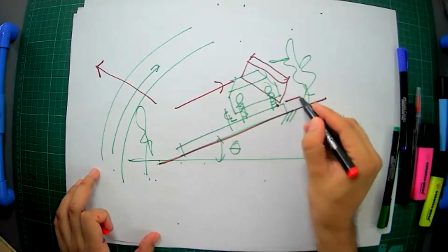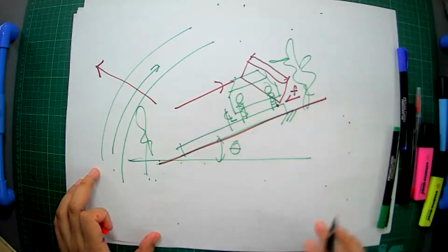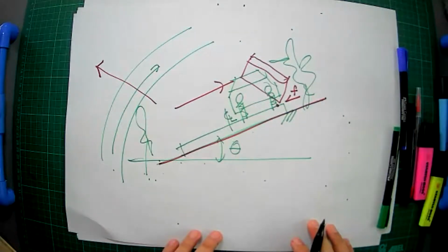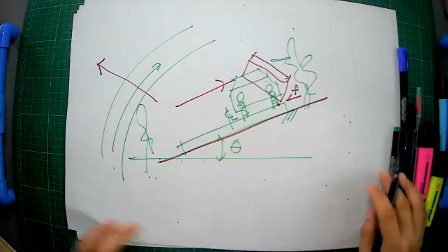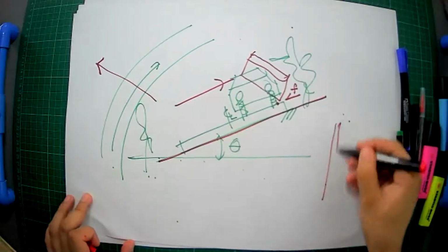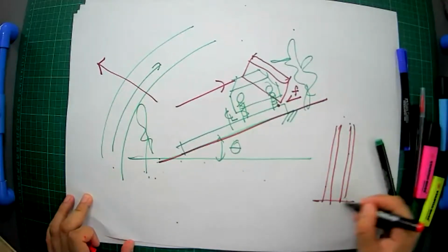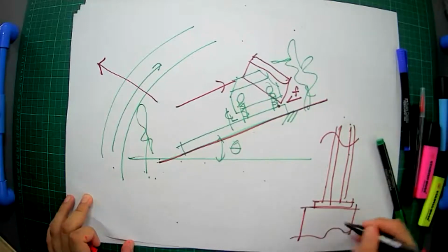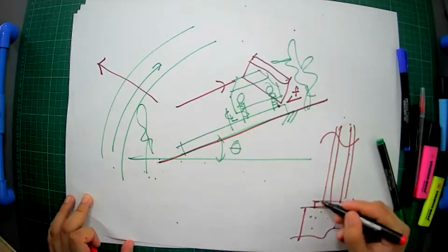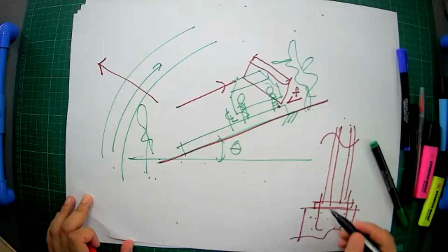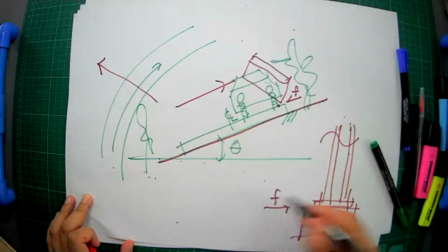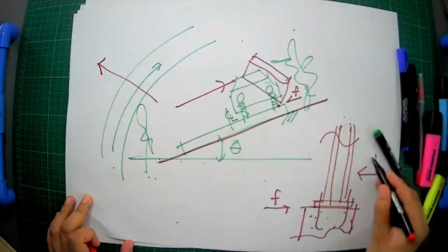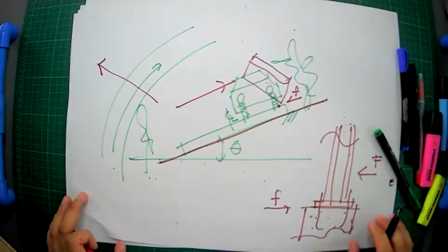At the same time, there is a considerable effect from your friction. Okay? So friction is very important in our study. Even our columns later, the steel columns on base plates resting on top of a concrete pedestal with anchor bolts, will somehow rely on friction, especially if there is a force acting opposite.